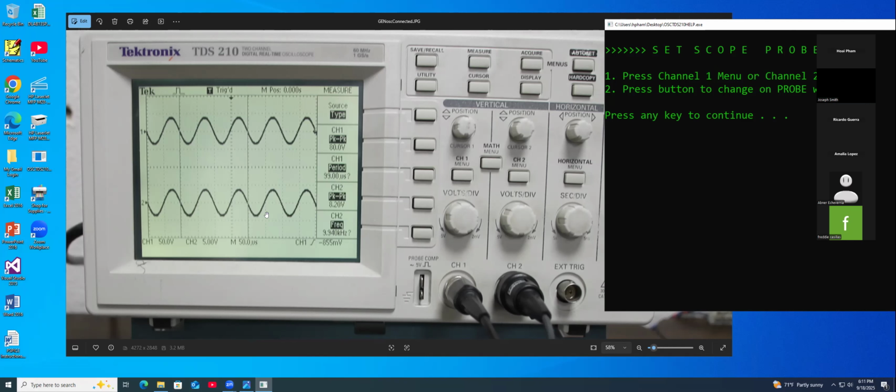They're using an analog scope, and that is not really good at this time. At this time, most companies use a digital scope. The thing is cheaper now. So we don't care. On the left one, they say set 10x probe and set how many volts per division. We just care what voltage they want. Then you can set it.